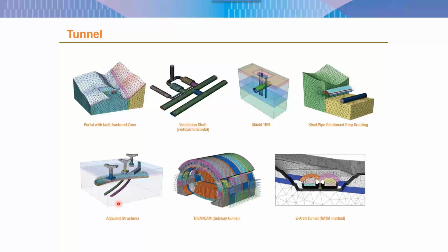So the main study that was done in this model was to check for what kind of extra stresses are developed or what is the externally induced shear zone or plastic zone around the foundation piles and also the pile caps for the bridge foundation due to creation of the new up and down tunnels. Then you can go for the subway tunnel with forepoling or crown improvement.